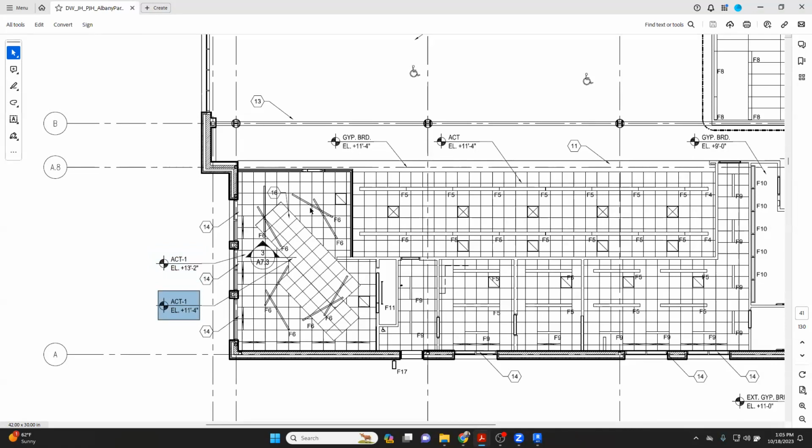Kind of like what you see at Starbucks, except Starbucks typically doesn't have the high ceiling. It's exposed to the trusses, the rafters above. But they decided to put a ceiling up top and then put a lower ceiling beneath it, so you don't see all the mechanical, ducts and what have you above. So there's 2 ceilings here. So you design 2 ceilings, but there's a trick here, because if you look at this drawing, this is at 11'4", right there.